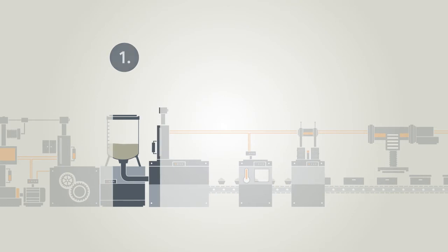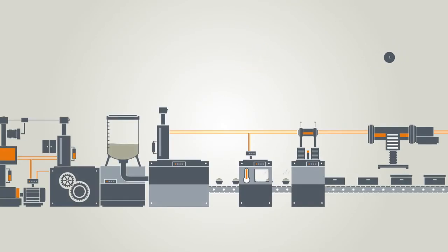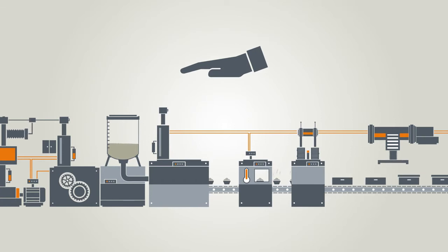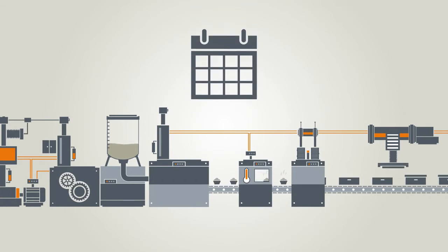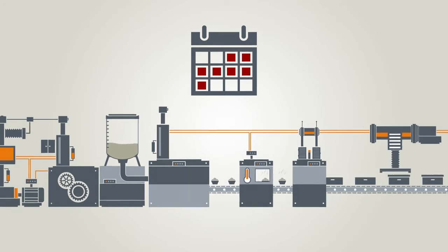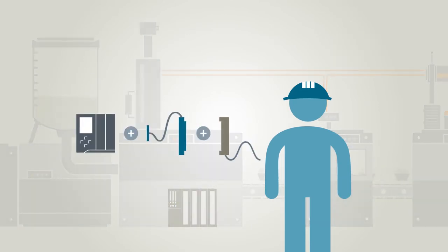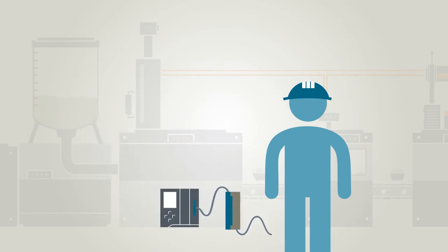You should modernize your plant in stages. This will minimize any risks. It is important that your planning should also take into consideration non-production time periods for commissioning. Use peripheral adapters as a fallback strategy. They enable automation components to be quickly removed without wiring outlay.